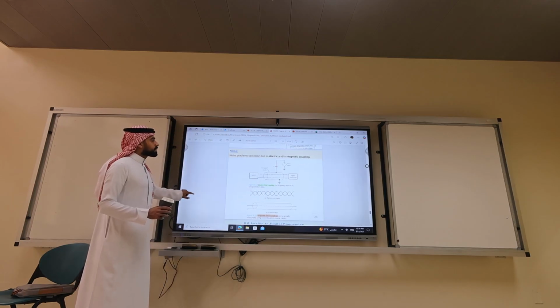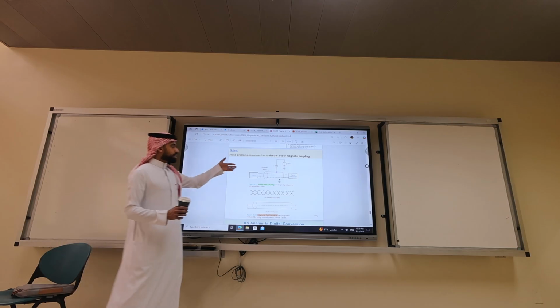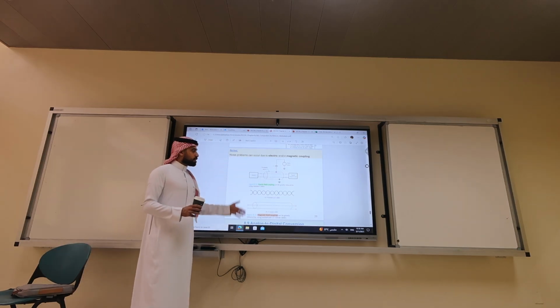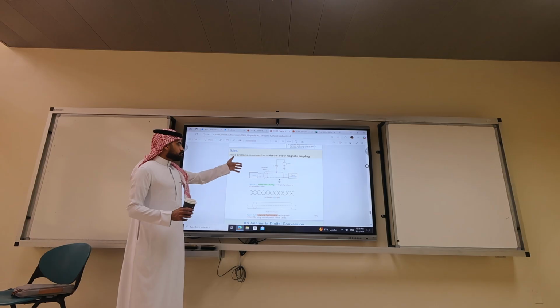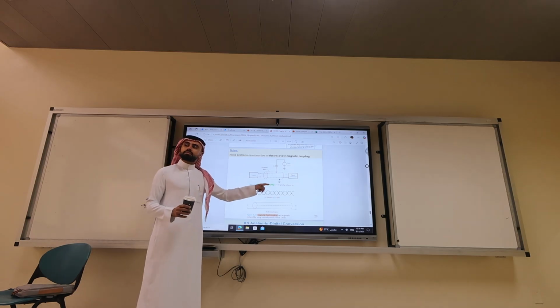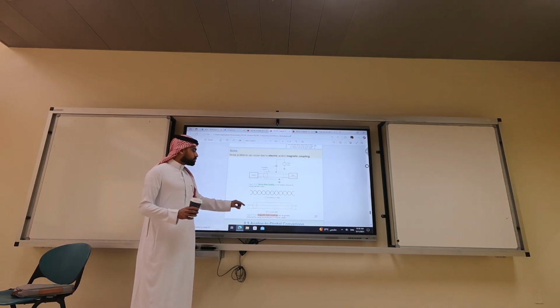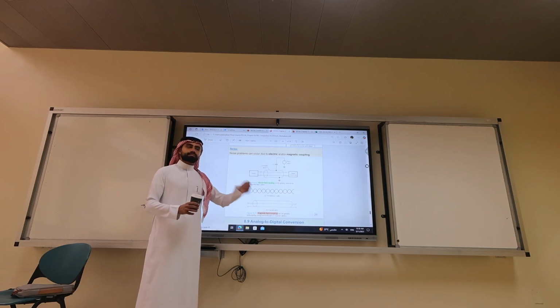If you have problems with noise, it can be either electric or magnetic. With electric, we use shielded cables. With magnetic, we use twisted pair cables.